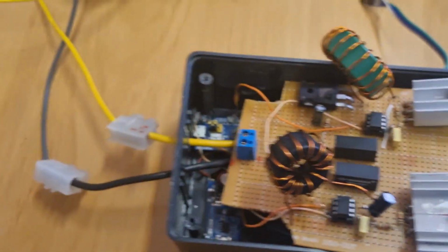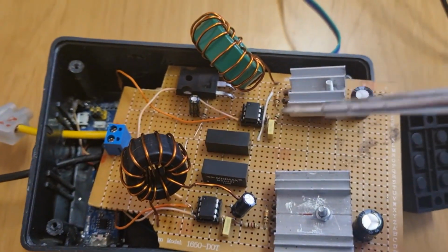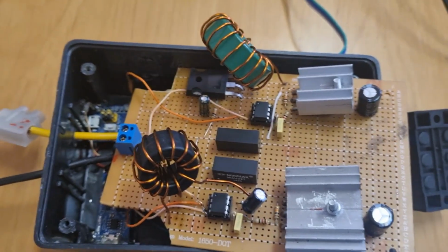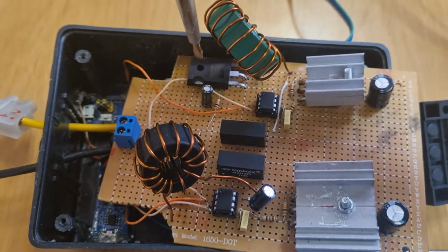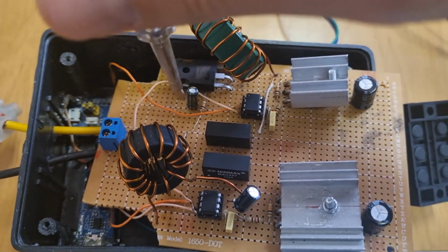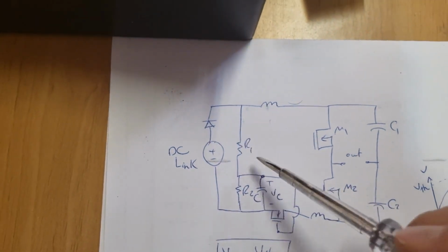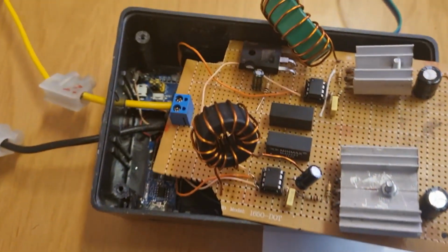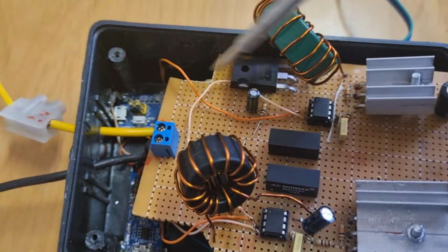And the output port is here and the input port is here, and these are gate driver circuits that I use, with min max for preparing isolated voltage supply for these switches. And this is the switch that I used, and this capacitor and these resistors, this one R1, R2 and C capacitor, that I used as an inrush current limiter here.